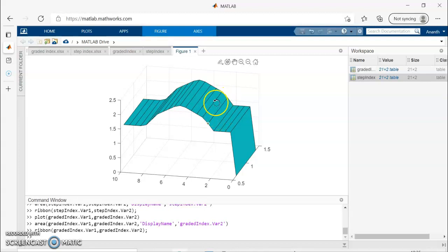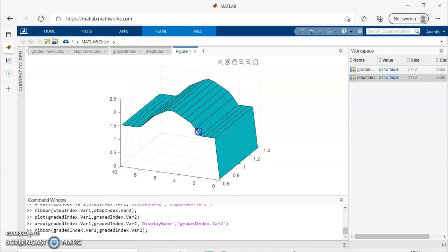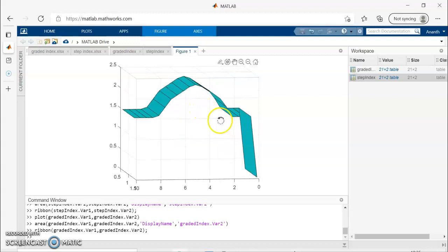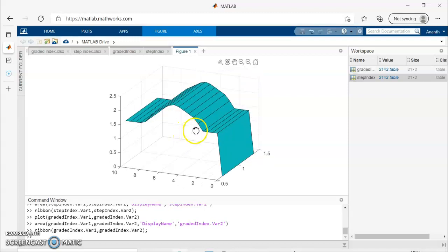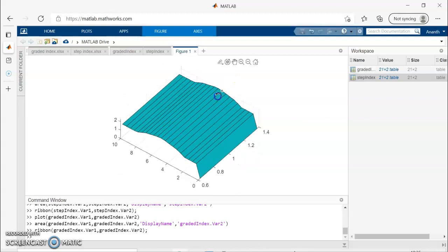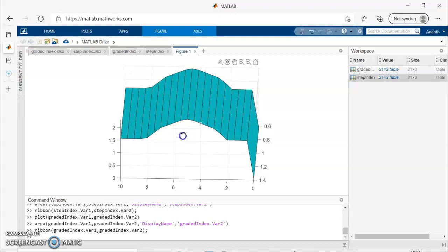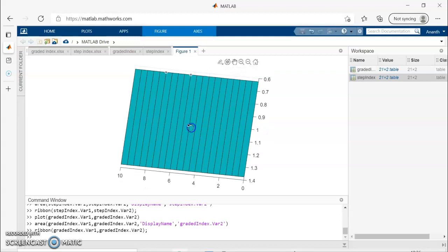So once again one total internal reflection happens. Then in the next layer, the previous core now acts as a cladding because its refractive index is lesser than the next layer. So in each layer, wherever the light goes, it produces one total internal reflection. Unlike the conventional fiber, where only one total internal reflection happens, here between each layer, because it is graded, a reflection is happening. This is the specialty of this one. So this concept eliminates the intermodal dispersion.